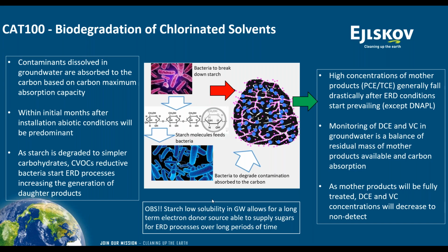One little advantage of having starch as an electron donor source is that starch has a very low solubility in groundwater. So once installed, this allows us to have a long-term source of electron donor to maintain longevity for the ERD process.